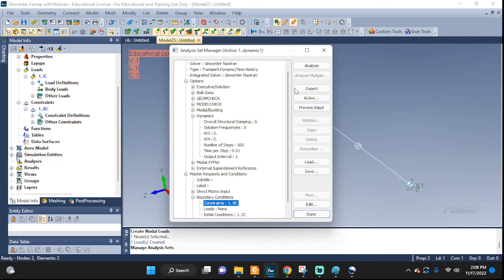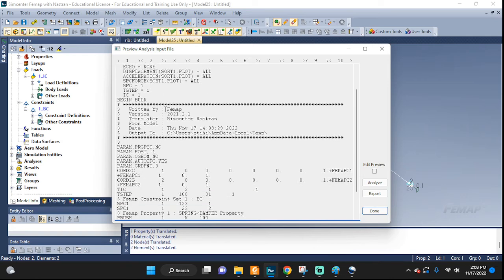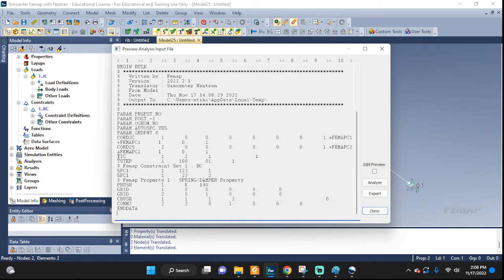Now we have entered everything that we need to enter, and you can run analyze, or before you start that, you can preview your input file. See, it brings up all the data, and you can check over here. See, over here, initial conditions. The 0.1 is our initial velocity, and this right here where there's nothing shows that our initial displacement is basically 0, what we set up, right? We can also tell here the C bush, what we selected, and other data.